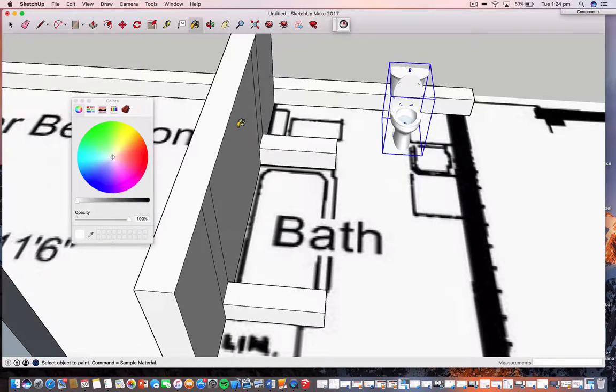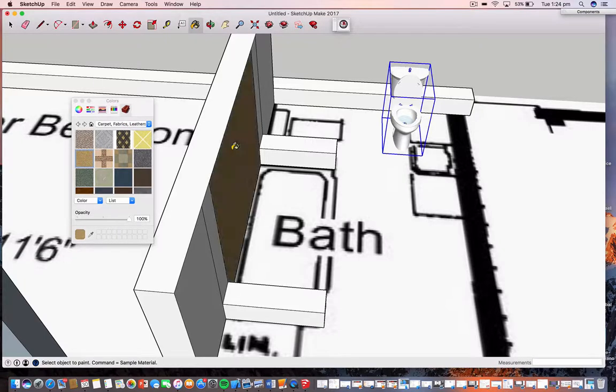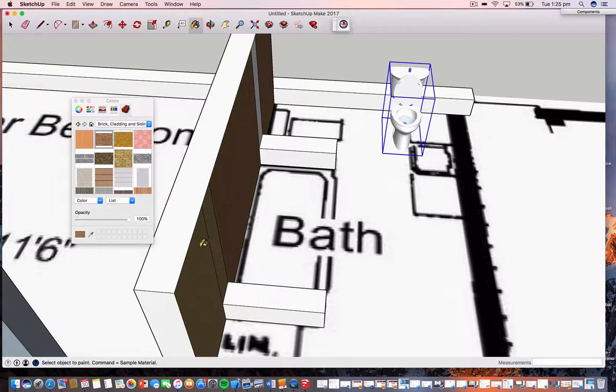So if you add a wall texture, and we want it to be a brick wall, none of those will show up, and you'll end up with strange grey objects which don't show up very well in the augmented reality world. So remember, if you add textures, if you use models, they have textures in them. Make sure you drag that textures folder into the same model resource as you drop the model into.